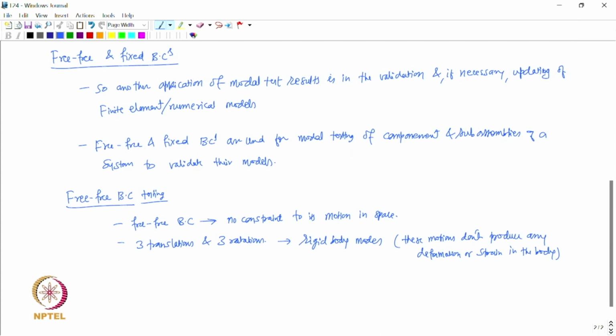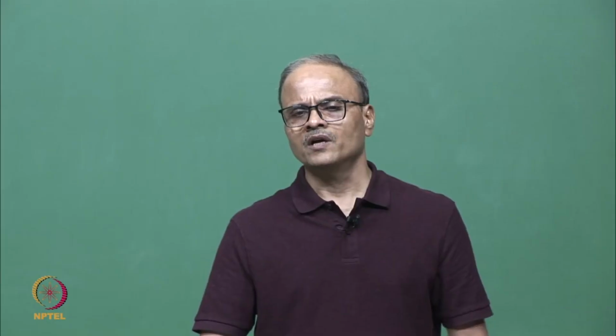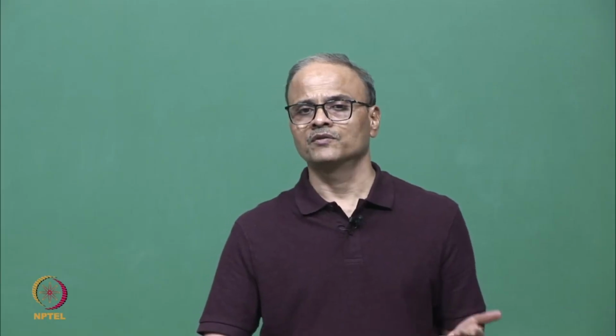And because in these motions there are no elastic forces which resist the motion of the body, because the body is free. So there are no external elastic forces acting on the body, and hence the natural frequency of motion in these modes is 0.